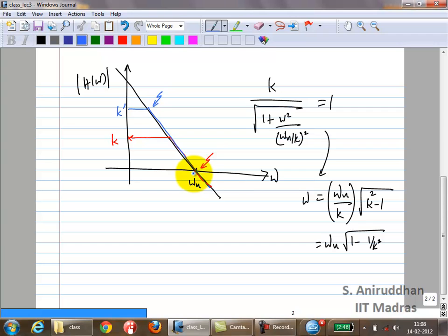Okay. Now given an amplification k, so let's say you want to build an amplifier k. What would you do? If you want to maximize bandwidth, what do you do? Obviously there is only one way to do it, which is to increase the integrator speed. So that is where your circuit design concern comes, right? So in a given process you want to build a very, very fast integrator. Now that has other obviously process related concerns. Okay, we'll come to that later.